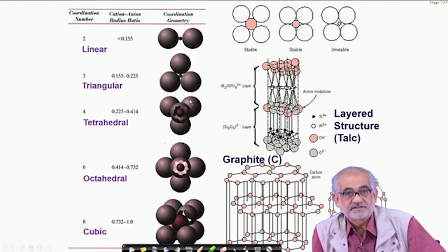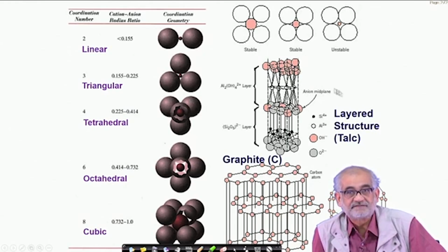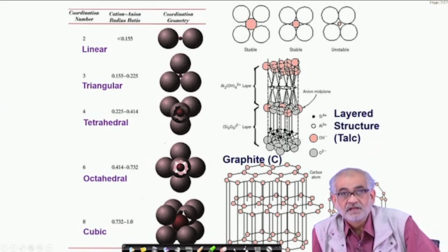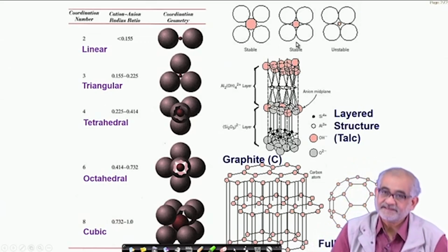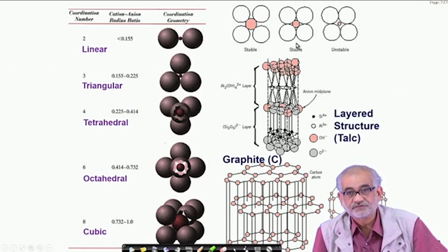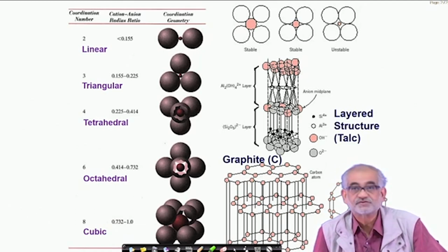So this is when you have complete crystallinity, but you may also have semi-crystallinity. For example, you can have layered structures, which we see in the natural crystal called talc, where we have these kinds of layers, and in between layers we have weaker bonds, and also dissimilar species. So as a result, these kinds of structures, even including graphite, are actually very good lubricants. So you see complete crystallinity in plane, but across the plane the crystallinity is not continued. We must realize that for all these descriptions, we essentially are trying to understand what kind of structure will be very stable and useful for developing crystals and developing solids, even non-crystals, which are useful to mankind.